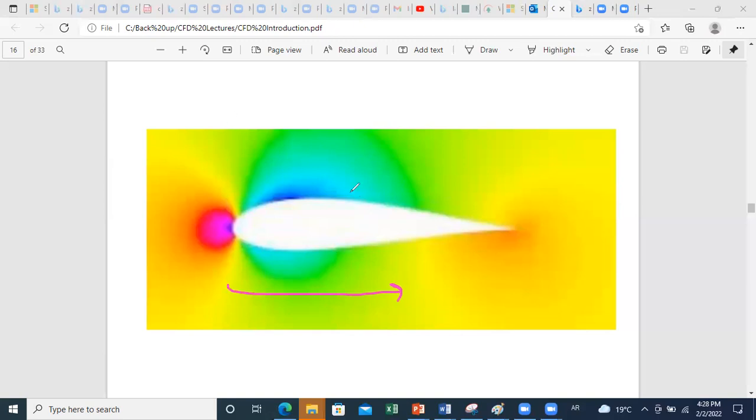Notice here, for example, you have this zone whose thickness is smaller than the thickness below, right? The less the thickness, the larger the velocity on top will be. So reducing the thickness here compared to the other, the velocity here will be larger, so the pressure will be lower. You can design it so that, compared to the center line, this part is shorter than that part, which creates in this zone velocities that are larger and pressures that are lower, and below it is the opposite. So this will create a delta P in this direction and this is what you want to do. That is the idea.